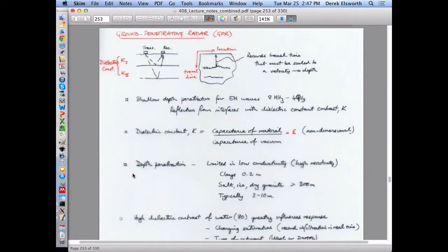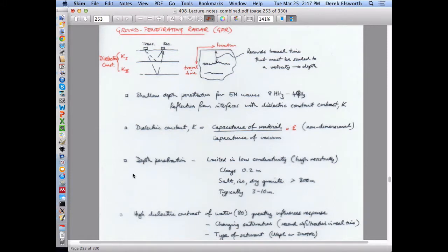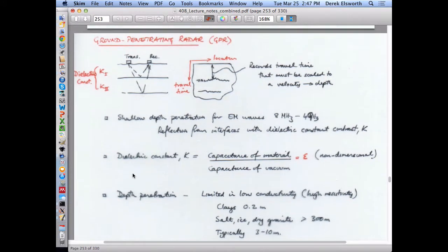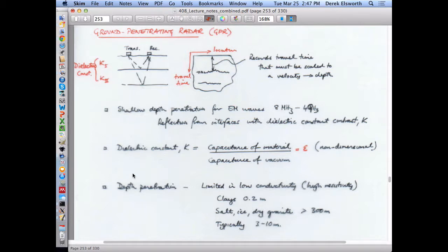But the one method which is used quite broadly in the environmental areas is GPR. It's no different than the radar that's used to pick up aircraft, just different frequencies. Typically you have a transmitter that sends a continuous pulse of waves pushed into the ground. You have a receiver which is separate from that. They may physically be separate objects, or they may be in the same object.